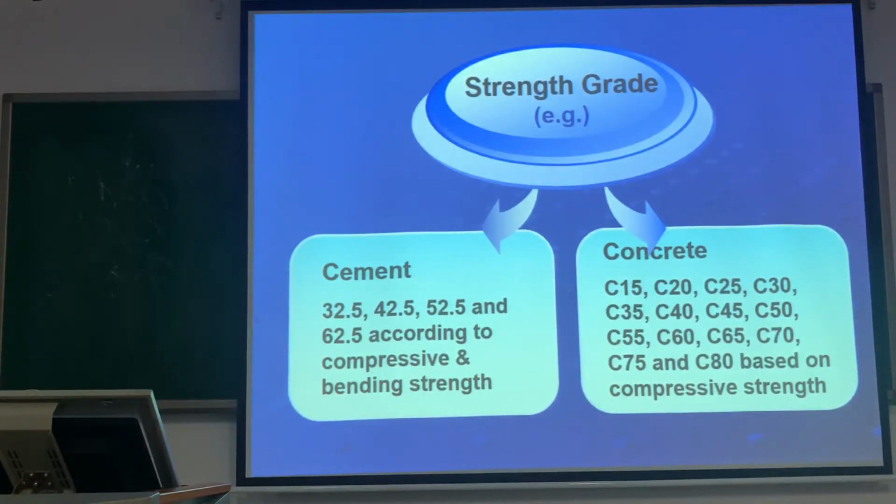I have to build a building here, but I have to bring concrete from Central City. Oh, you mean the transportation? Yes. For the transportation, if the distance is very long, you must add admixture.